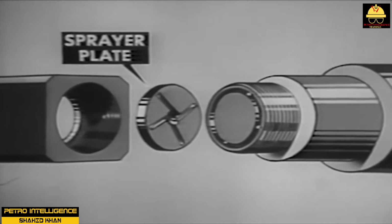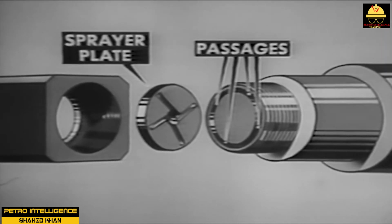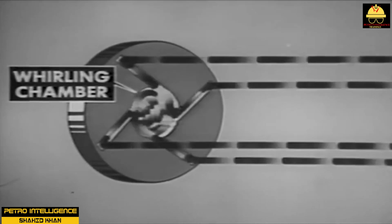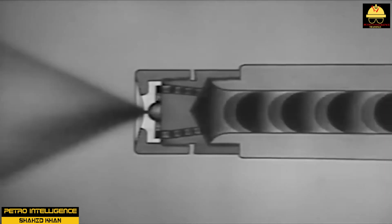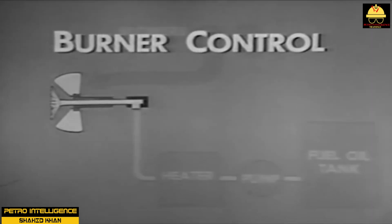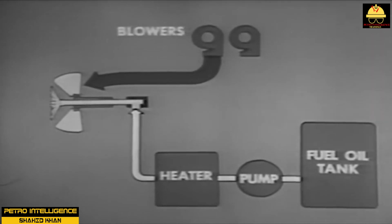A fuel pressure control loop is located on the natural gas fuel line to the furnace that is designed to maintain constant pressure to the furnace burners. The perfect mixing of air and fuel is impossible, and no practical way has been found to determine when the combustion process is complete. Incomplete combustion indicates that unburned vapors will be present in the hot combustion gases. To be on the safe side, most facilities use excess air to ensure all of the fuel has been burned.